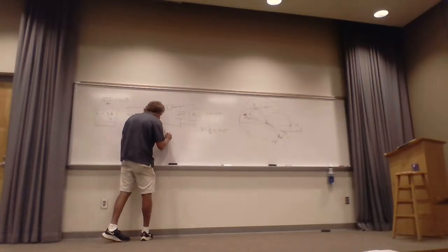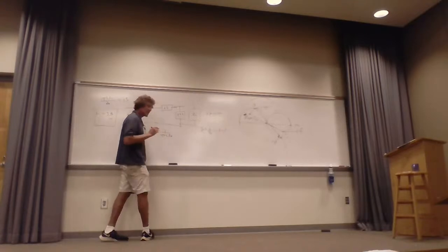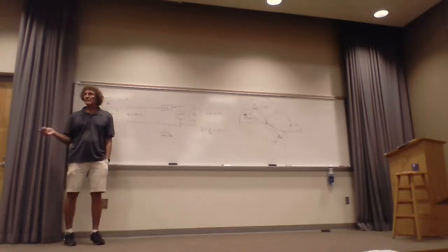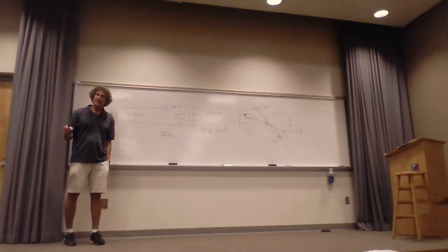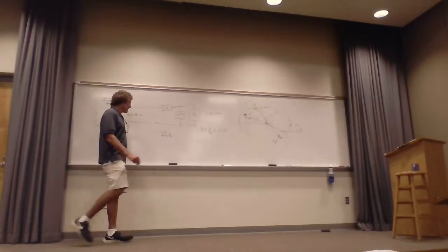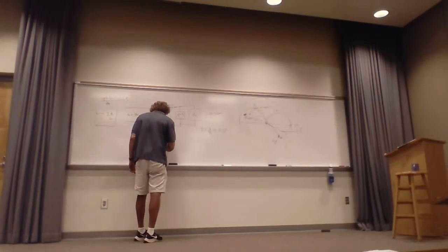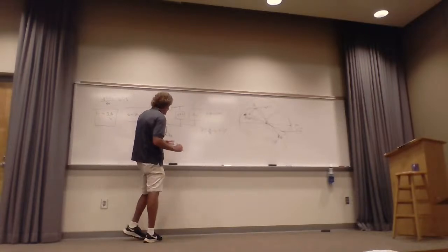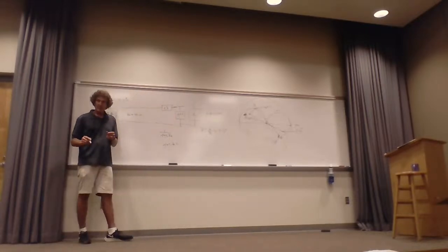That means I divide by Z naught, right? Now that's still a normalized impedance, right? But that's an admittance value, so now I take 1 over everything, and now I say j omega C times Z naught. Well, that's what j0.2 is.